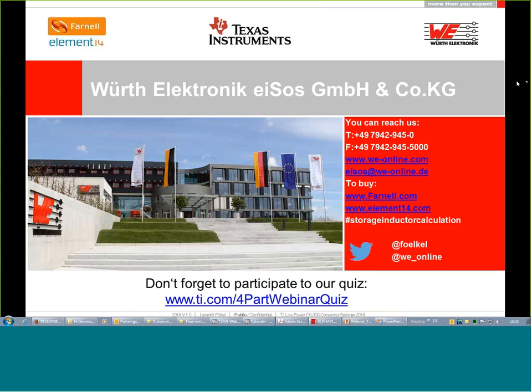Thank you, Jane. So somebody asked here, can you advise the topology for high gain DC-DC booster about 20 times amplification, current about 10-15 milliamp, a very, very low current, very high amplification. So in this case, definitely I will use a transformer and not just a simple DC-DC by inductor.